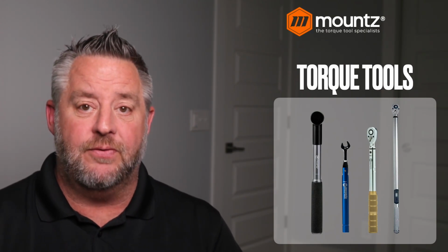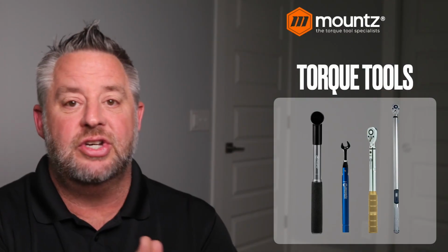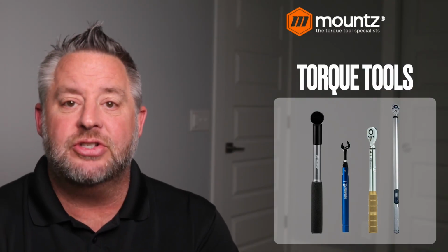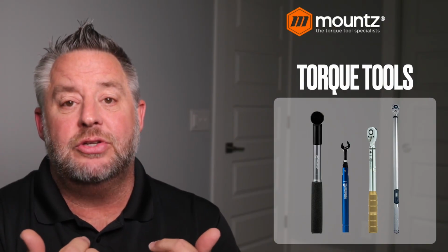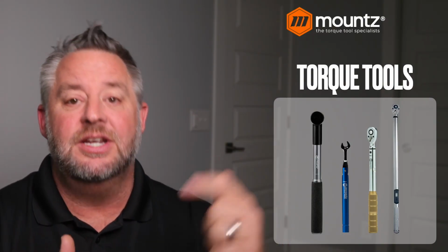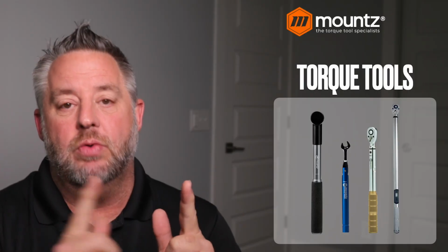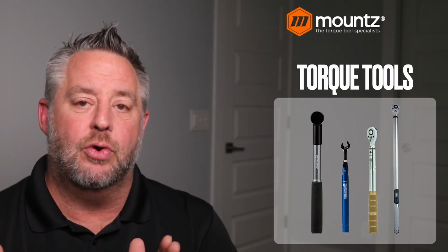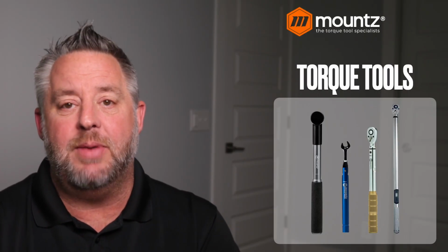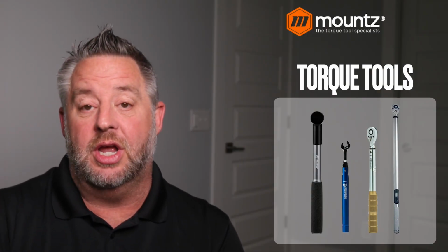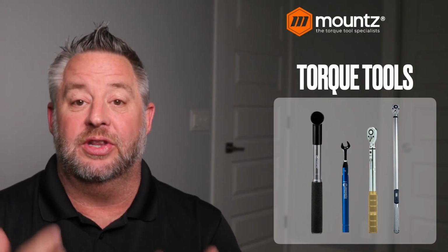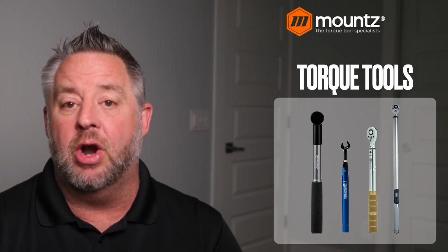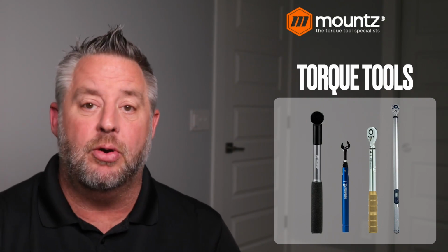Now that's going to be different for the breakover wrench and the click wrench, because our fulcrum point is down inside of the tool, not at the end. It changes that ratio that happens with our distance times force. And so if we were to grab a click wrench, there's usually a mark on the handle that's telling you where to pull from.